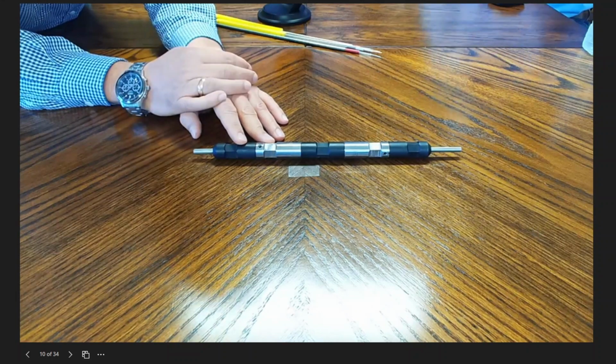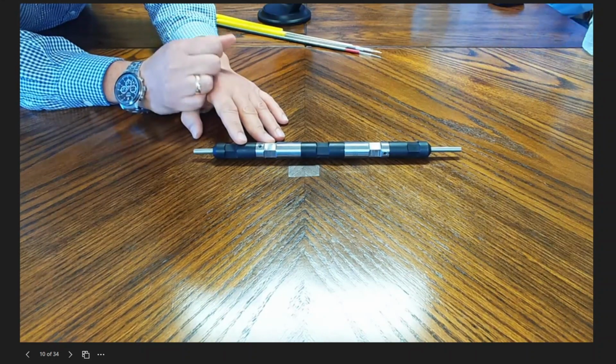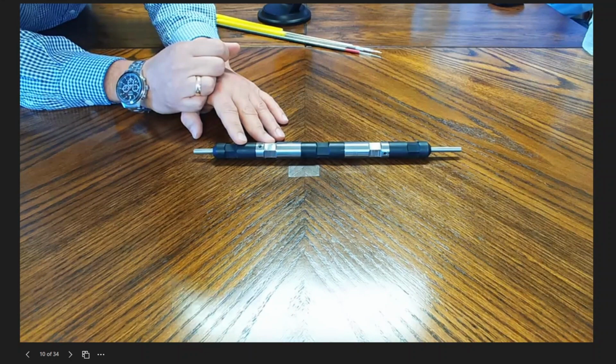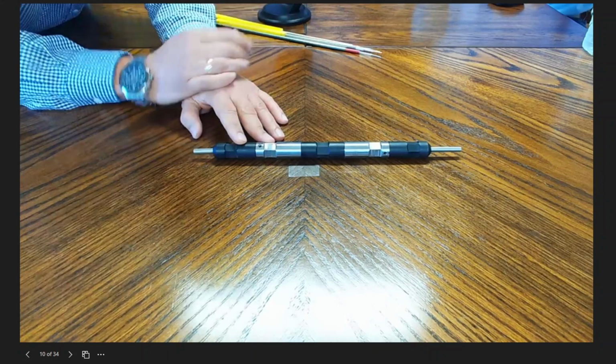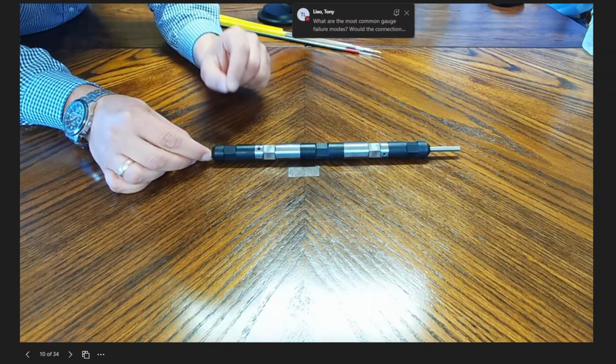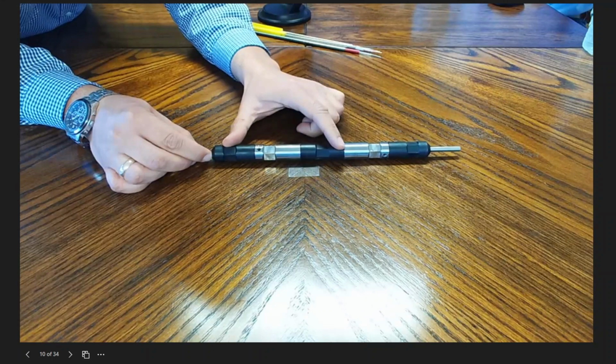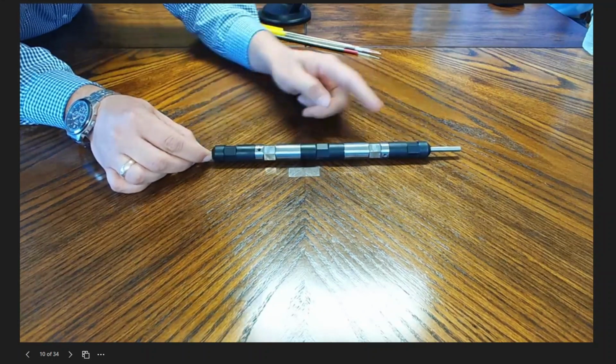And as we run in the hole, people could potentially make mistakes. We could have issues like somebody not pulling the TEC aside and hitting it with a power tong, or the tool pusher or rig operator closing the slips before we pull the cable away, physically damaging that TEC cable. Yes. When things like that occur, in order to avoid pulling out and starting over the installation, you have to have a particular way to repair that cable. In order to do that, we have developed this splice kit that essentially allows that repair.